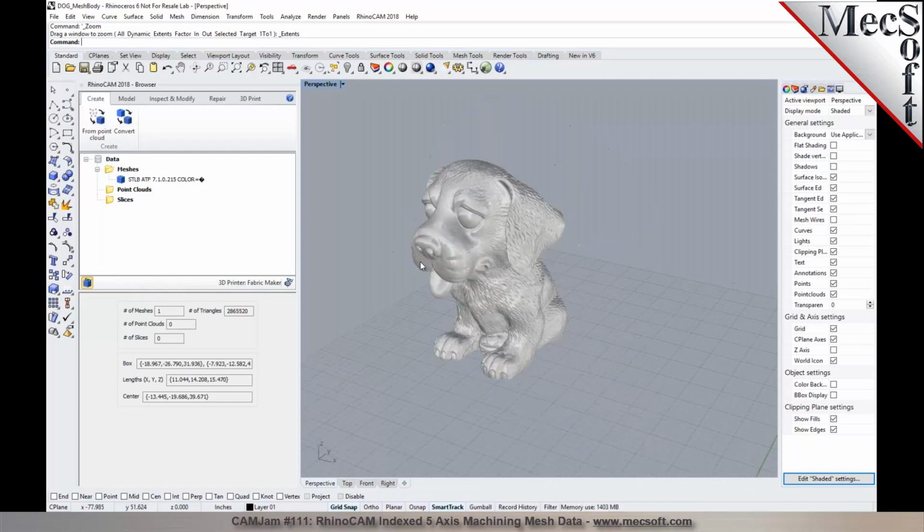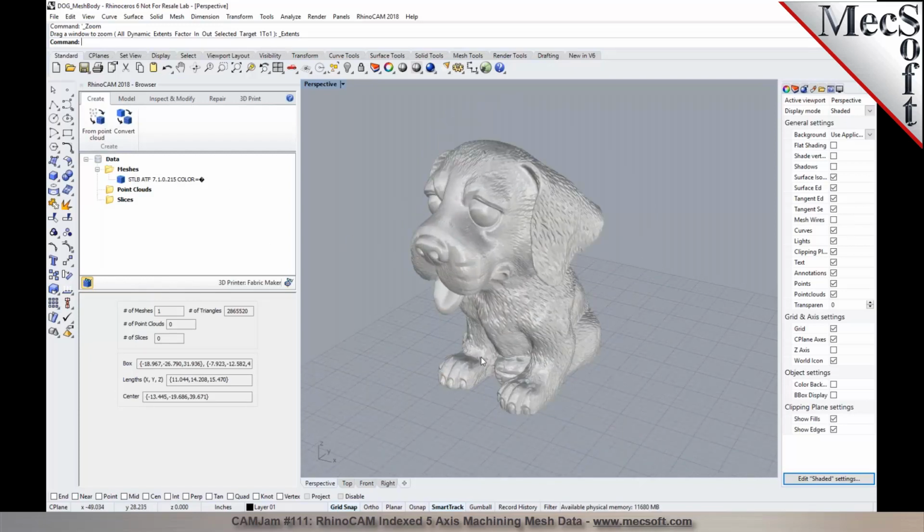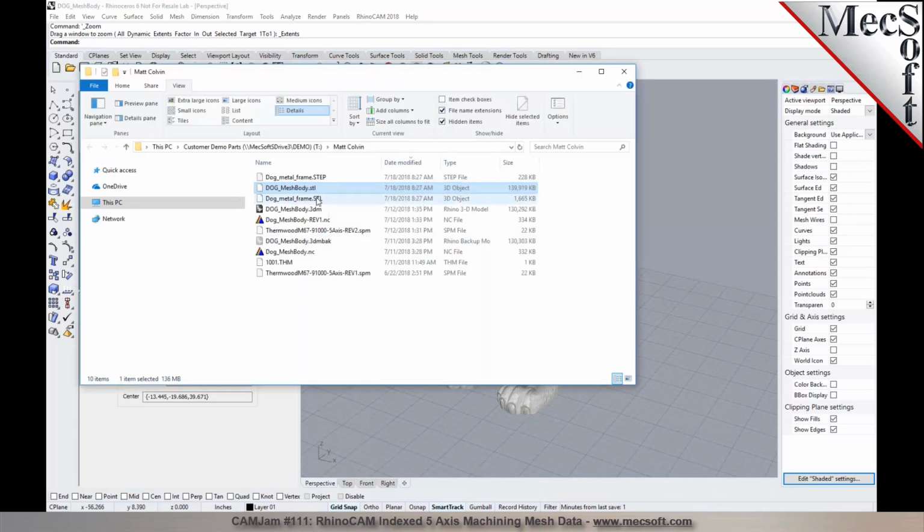Okay. Yep. All right. Now, are there any additional geometries we need to import into it? Yeah, so the two other files are identical files. One's a step file and one's an STL. Okay. Which one would you rather work with? If you have an STL, we can just take that in there, because we don't have to convert from a surface or a solid to a mesh.